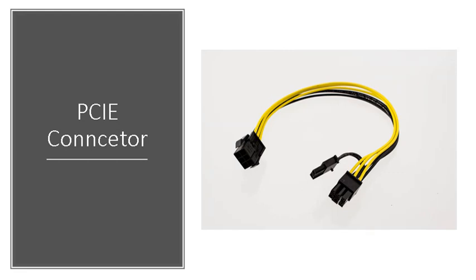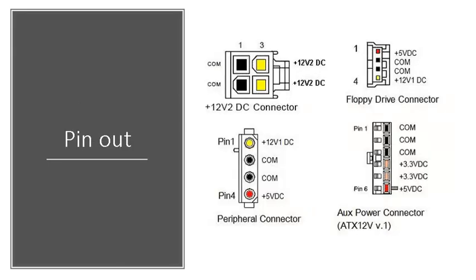And now we're going to learn about how to troubleshoot your power supply if it wasn't working correctly. You want to figure out where the problem is and what is not working. So one of the ways to do that is to always have access to the pinout. You can just easily search it on Google. For example, for your Peripheral Connector, you search for Molex connectors and anything like that to see the pinout.